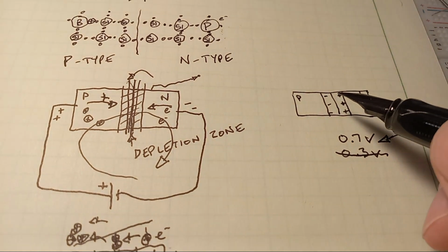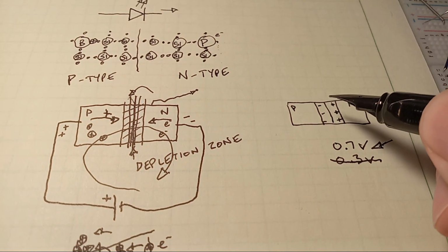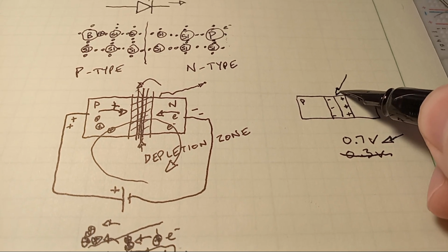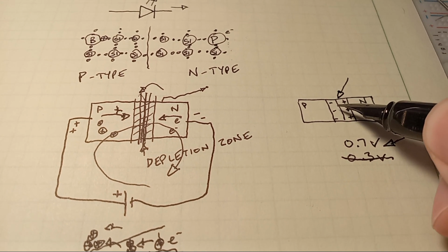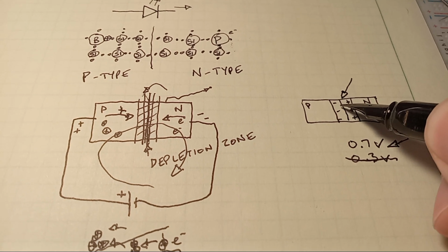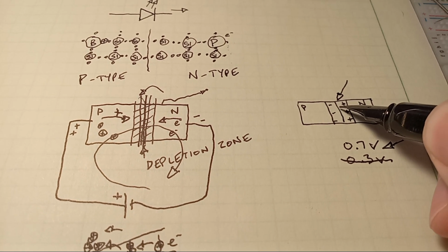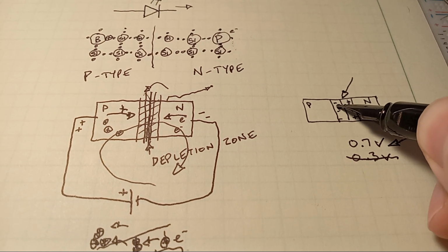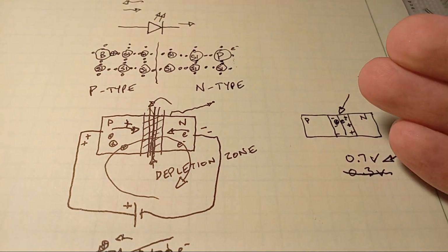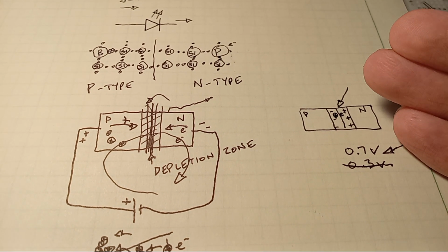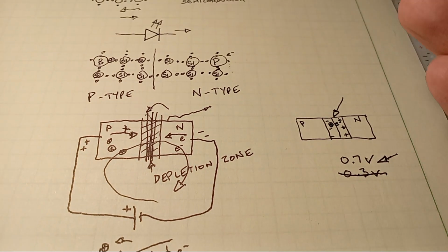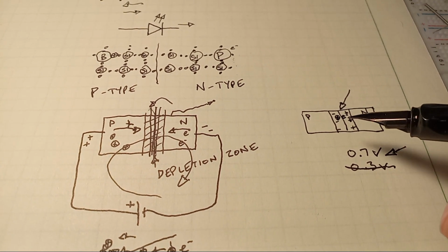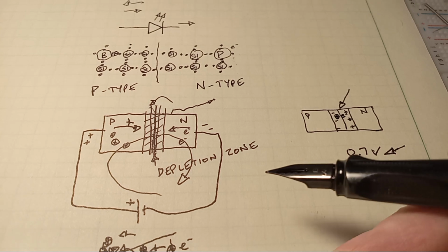But back to this little space charge region. Let's imagine we were running an LED backwards. You want to send a photon in instead of having them come out. This photon smacks into an electron that's associated with an atom, splitting it into an electron and a hole, splitting the location that was occupied by the electron in the crystal structure. That is, it smacks an electron out of place. Where the electron was, a hole is left, and of course there's the original electron still wandering around somewhere.